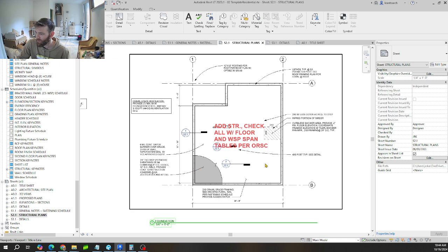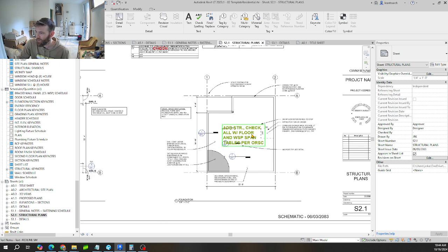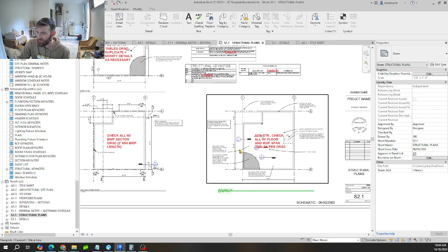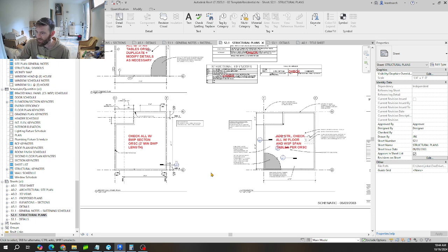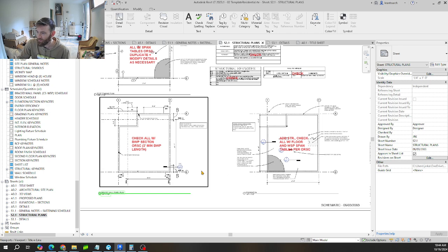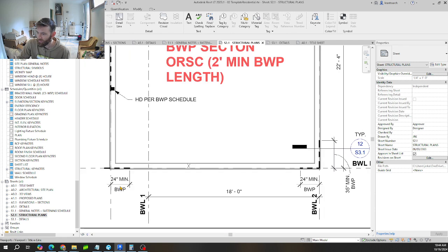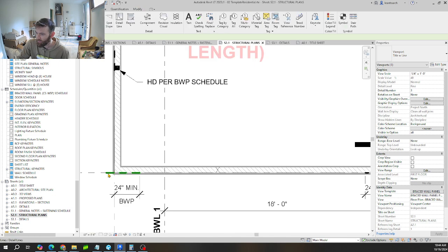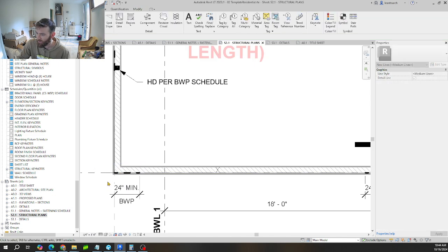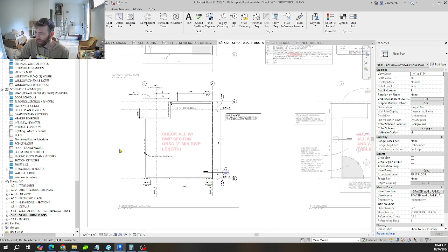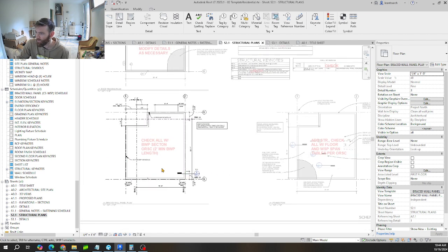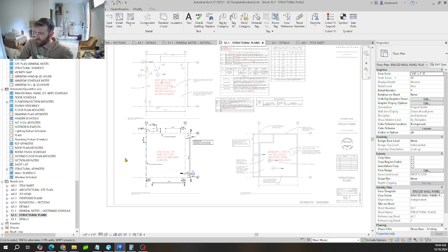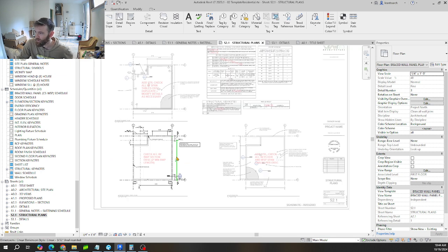Floor plan as well, showing your joists or girders drawn in, your spans and your limitations based on span tables in the residential code. Brace wall panels are minimum 24 inches. That line should be at the corner of the building there, and you have to check your brace wall panel section in your residential code to determine exactly what those are.